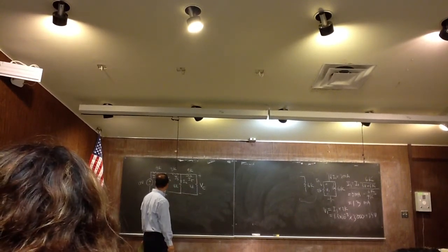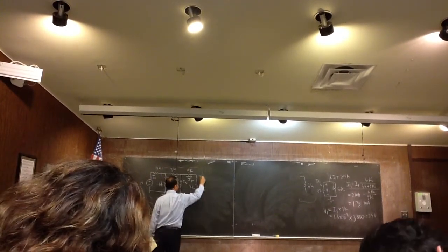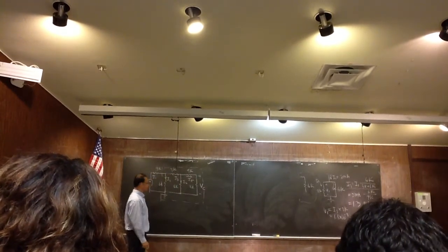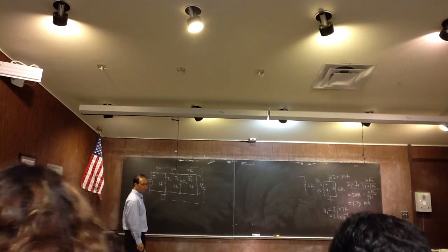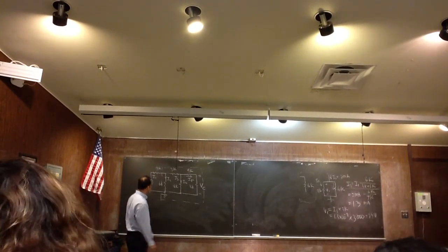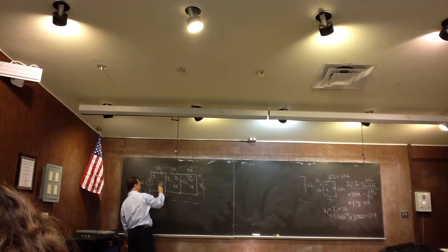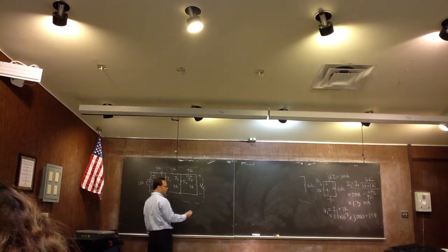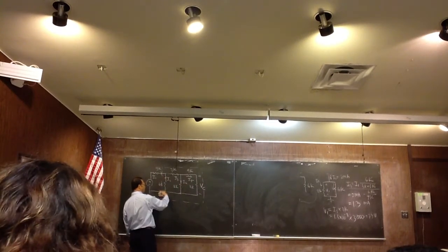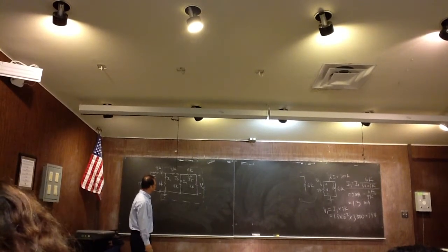Again, the best way to solve this is to find the equivalent resistance in that box. Because you are looking for the resistance from these two nodes, you should go from the opposite side, from the right hand side, and then gradually arrive at the node.